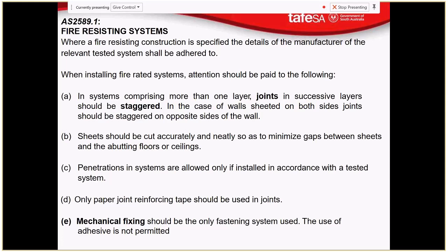Yep, exactly. So if we look at that in elevation, with our studs behind, we'll have our first sheet here, going over those two studs, and then our second sheet here, and then another row of studs there, and another sheet happening like that.